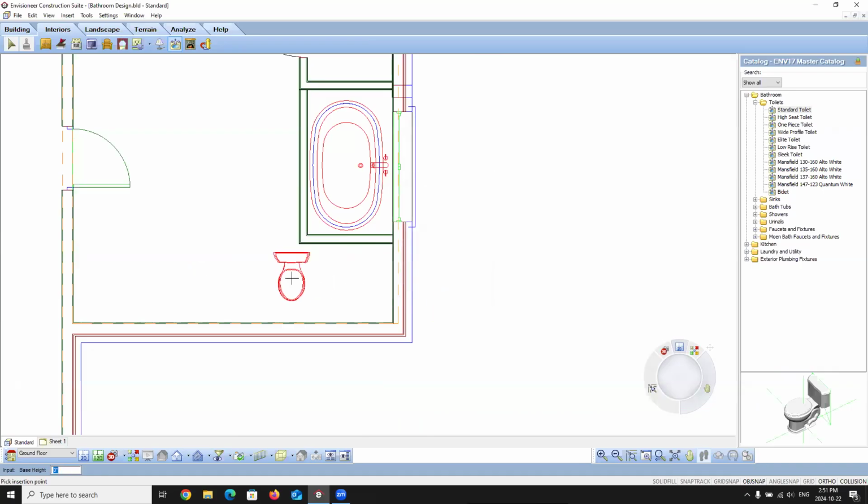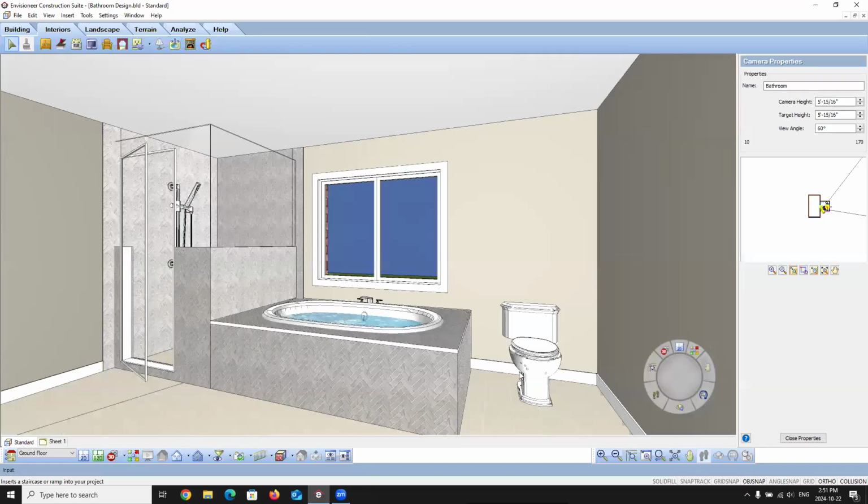And we're going to say, okay. So what that will do is, as you can see, I have plenty of room in here to move this toilet left and right because it's saying that is 11 inches from the tub surround, that's 11 inches from the wall, and we can see the 1 inch away from the back of the wall itself. So I can now place that toilet in, and it now sits that toilet exactly where we would want it to sit.